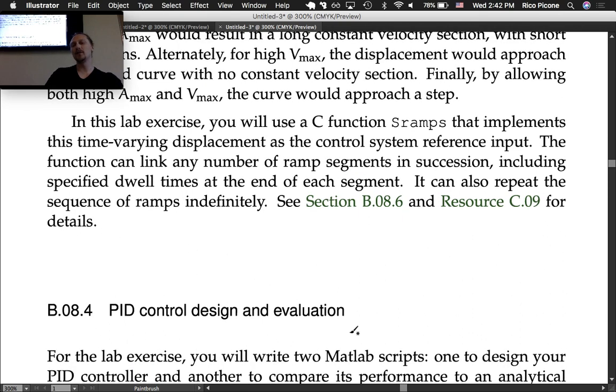Instead, what you could also do is just simply say, oh, my command is this now, and now I want the command to do something else instantly. You just change it from one time step to the next time step. But then you're going to saturate for a while. Yeah. So is the dwell time going to depend on how fast the motor gets there? No, it will. So it's based on the S-ramp time, the time it takes the S-ramp to go from one to the other. I don't think it takes into account the settling time.